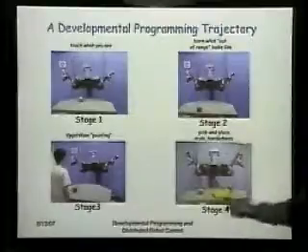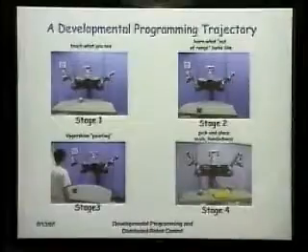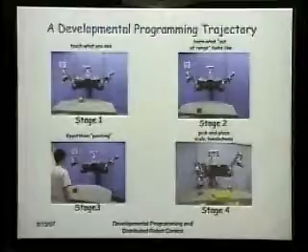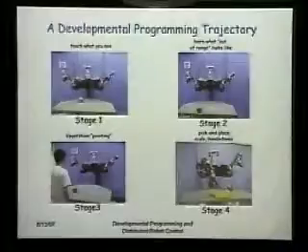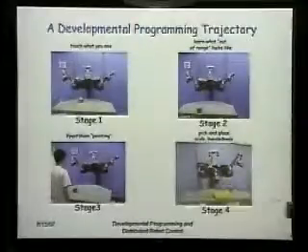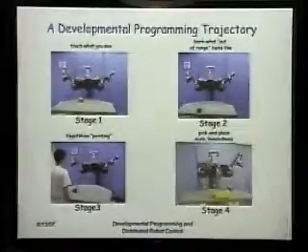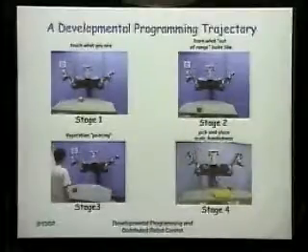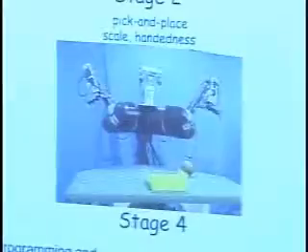It also knows about handedness. Things that are on the right, it uses its right arm for. Things that are on the left, it uses its left arm for. So it's making a query of the table. It finds another object which will satisfy the see and touch affordance that was also graspable with 1 hand, and it applies the right arm to go get it. And then it does the same thing. These are all just re-instantiations of the same general plan, the same general schema with different procedural details. I'll let this play out just to prove that he will go for that, and he will use the hand that he likes to use.